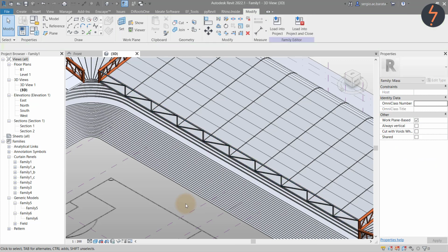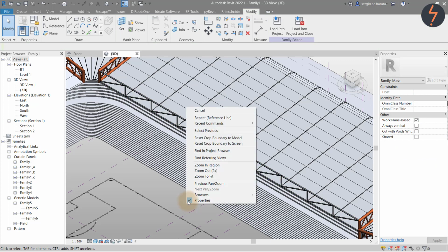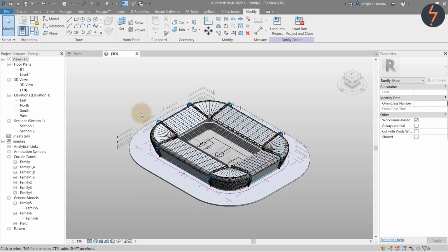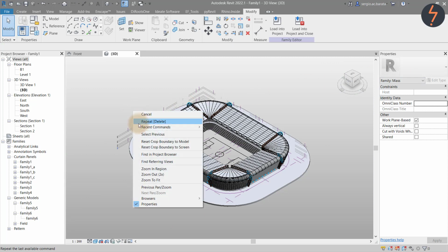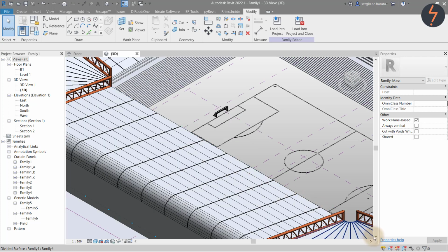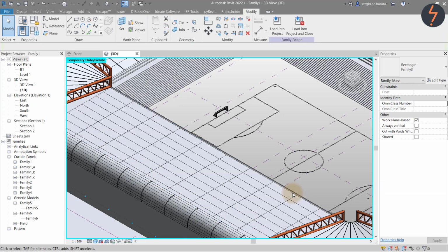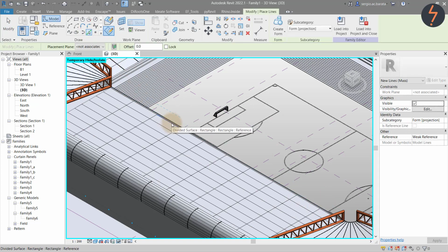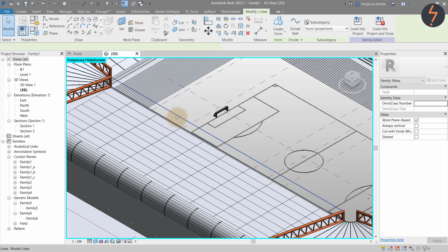Now that might not have been very clear, so I'll go through it once more, but this time on the other side. Let's zoom into our target area and deselect the pin icon on the selection tools. This will enable the roof to be picked and hidden. Then move back to the selection tools and toggle the pin to lock all pinned elements. Then from the draw tools, click the Pick Lines tool and find the roof form edge.